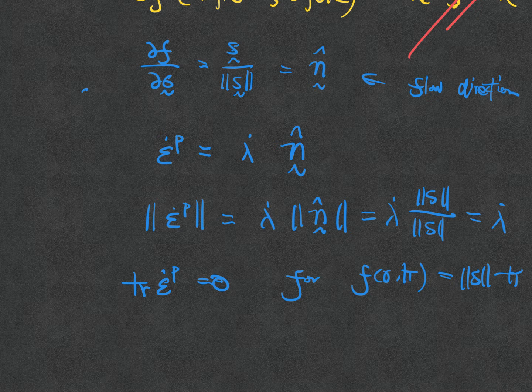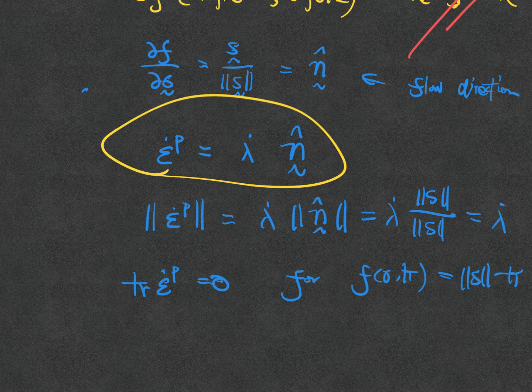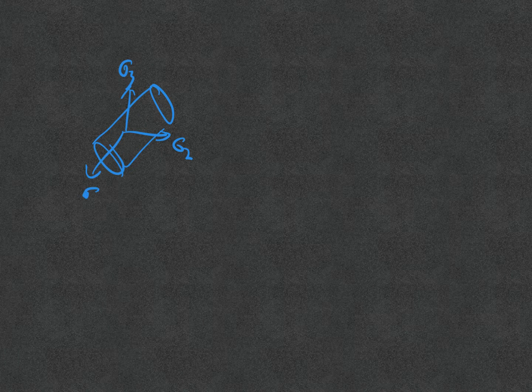I know that I can write the plastic strain like this, and I know that I can also write it another way. Now, plasticity theory is really abstract and hard to imagine, but to make it easier, one way is to think about it in geometrical terms. So in this case, I would have the yield stress that looks like this in the principal stress directions, and I would specify what perfect plasticity is here.